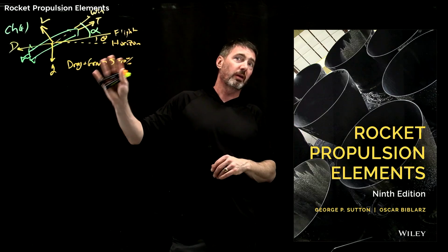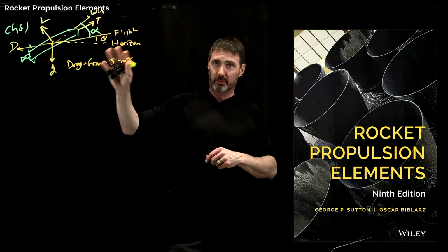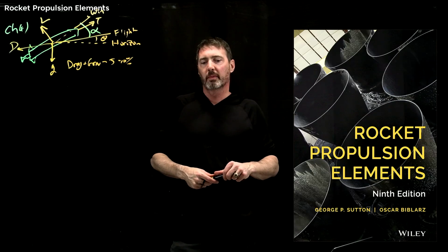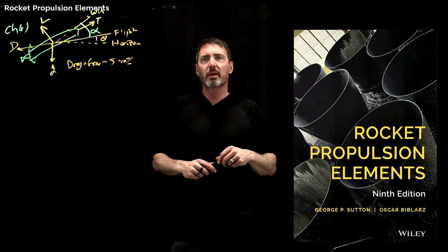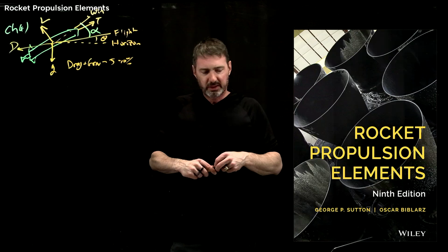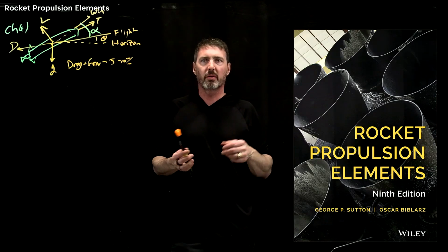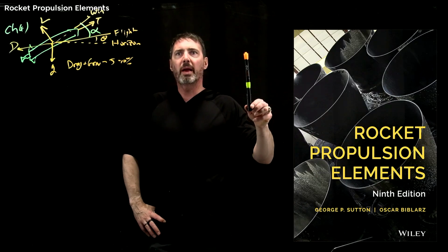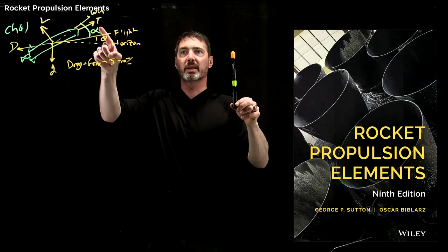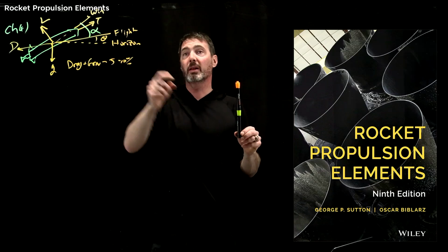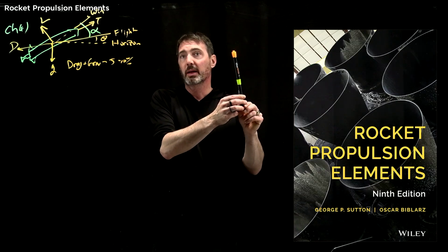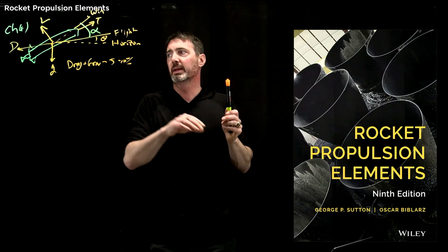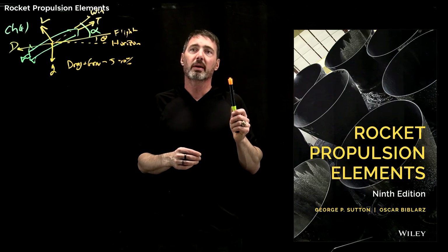This is really the start of making real rockets. You get into these details, and some of these things are, I'll just say, not easy. They're not impossible. They're just not easy. And what can happen a lot of times, we've been launching rockets for a while: a rocket that starts launching vertically and goes up might only have, say, a 3-degree angle of attack. And so the aerodynamics at a 3-degree angle of attack is actually pretty tame. So wind tunnel models and CFD are going to account well for the flight dynamics of it.